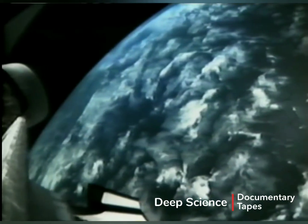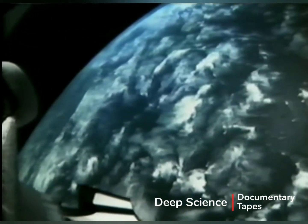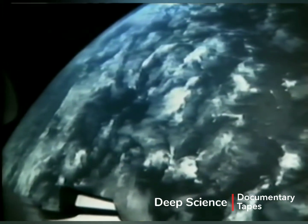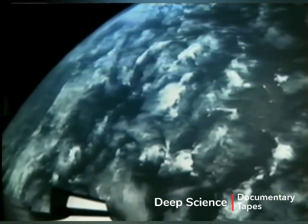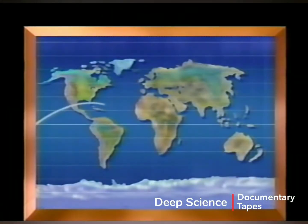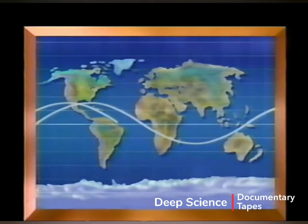The six orbital elements depict a spacecraft's orbit in non-rotating coordinates. To visualize an orbit relative to the rotating Earth, a projection traces the spacecraft's position on the Earth's surface. The projected path is called the ground track. As a satellite orbits the Earth, the ground track shifts westward. There are two causes for this.